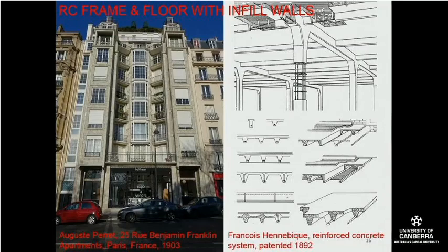So traditional buildings would have load-bearing walls, whereas these, like you can see here, these walls here are actually all infill. So really, you can get a bit of an idea despite the old-fashioned windows, but it was on the interior that you could really tell, because most of the walls on the interior could actually be placed anywhere on the floor plate, because the columns were actually taking the structure down the building.